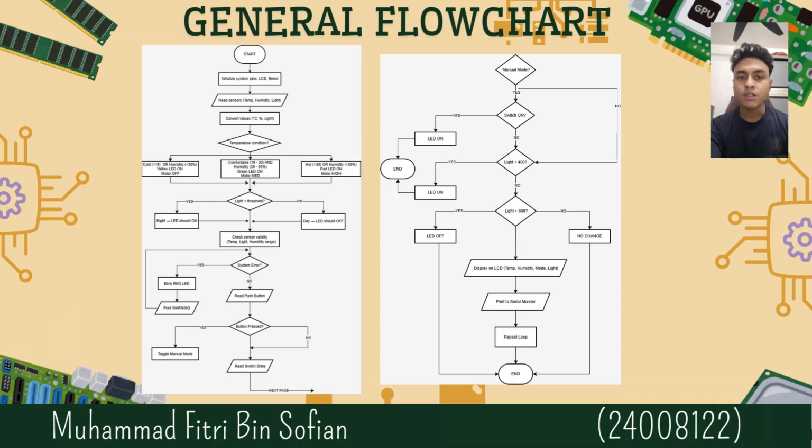If there is no error, the system reads the push button to toggle between manual and automatic mode. In manual mode, the user controls the light using a switch. In automatic mode, the system controls the light based on the light sensor value. Finally, all data is displayed on the LCD and printed to the serial monitor, so the process repeats continuously in a loop. After that, we end.